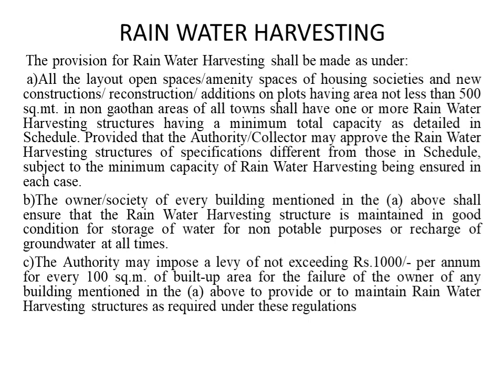Then the entrance landing. Entrance landing shall be provided adjacent to ramp with minimum dimension of 1800 mm by 2000 mm. The entrance landing that adjoins the top end of the slope shall be provided with floor material to attract the attention of visually impaired persons. Limited to colored floor material whose color and brightness is conspicuously different from that of surrounding floor material, or the material that emits different sound to guide visually impaired person, hereinafter referred as guiding floor material in Annexure 1.